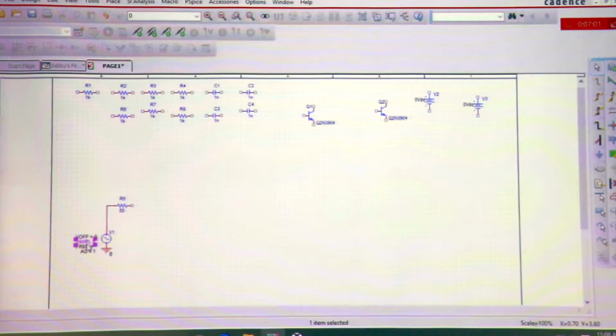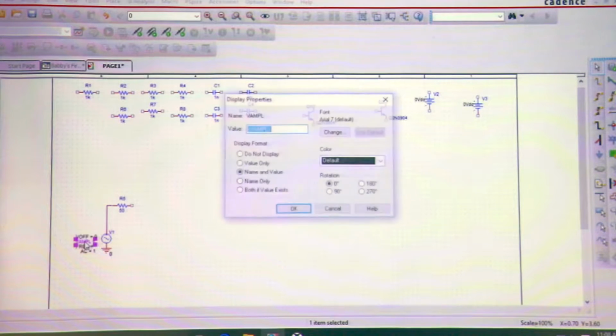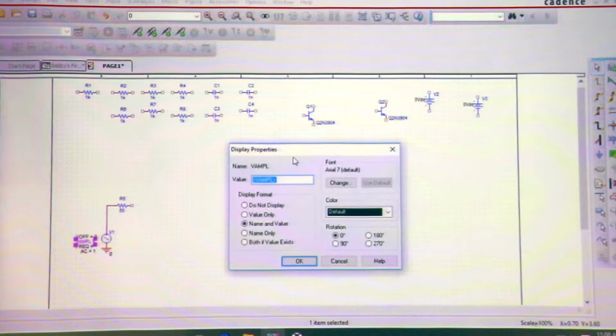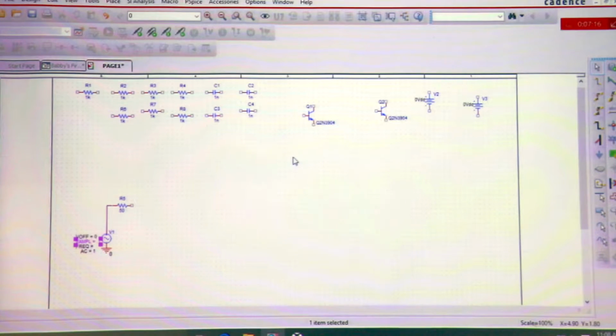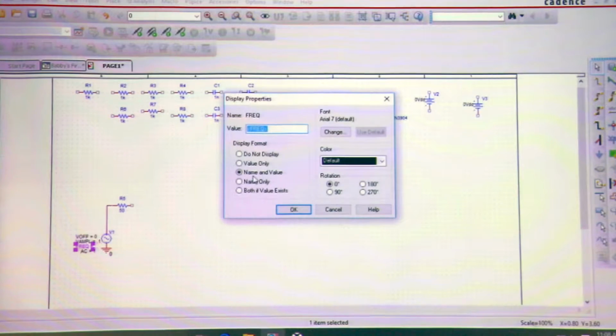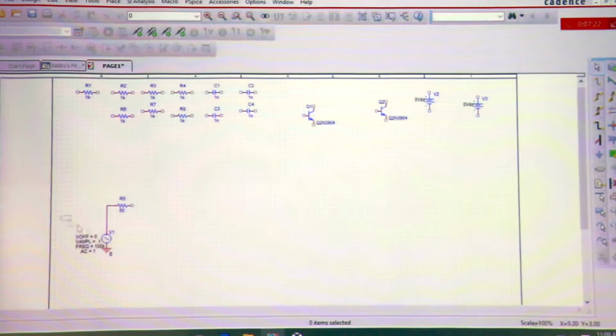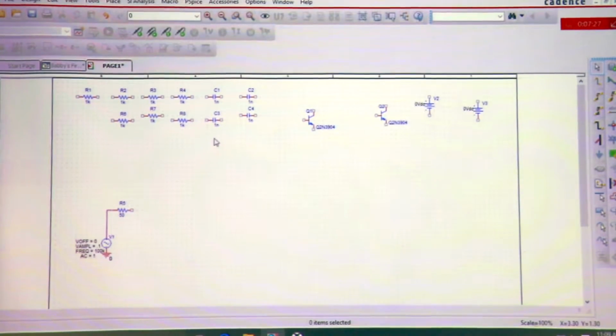And then in the middle, these two are for when you run a transient simulation. So this is what the voltage source will do when you simulate the whole circuit. So V amplitude is usually going to be something smaller because the real circuit is limited by your DC sources. So just make it like 0.1 and, I don't know, 100K or something for now. We'll fix it later. But that's a good place to start. And we'll continue building the circuit.